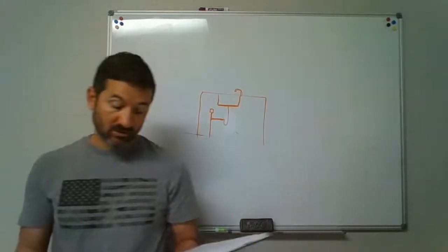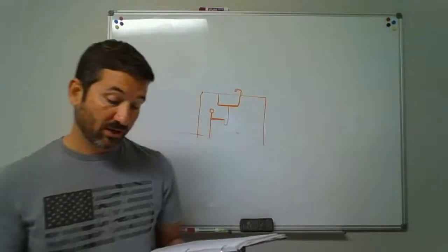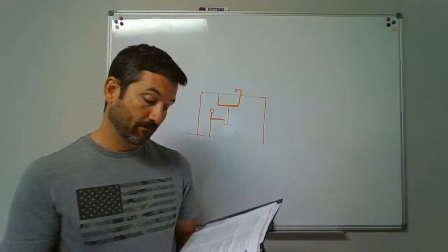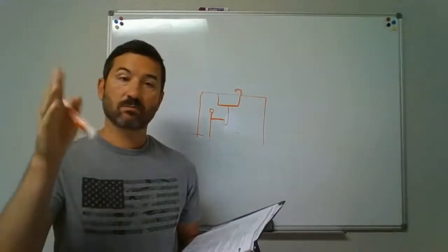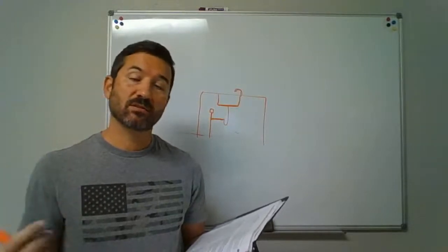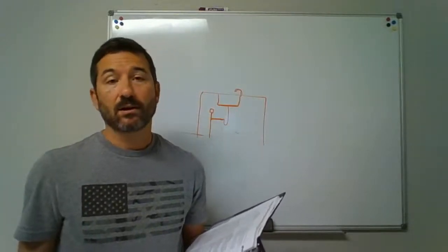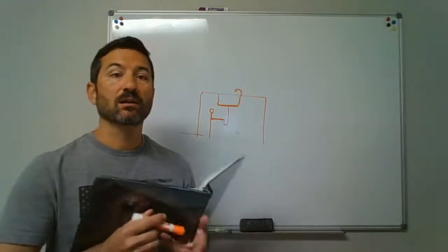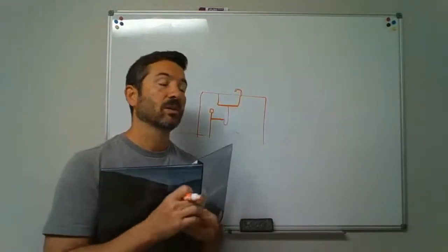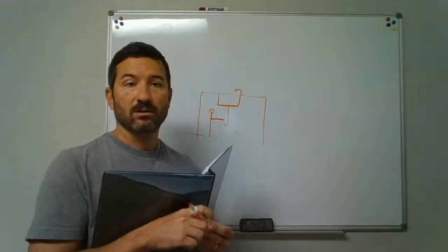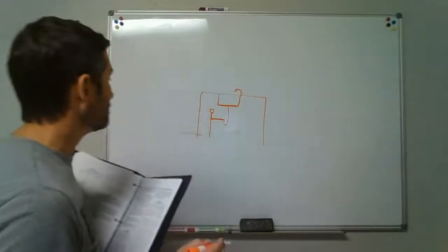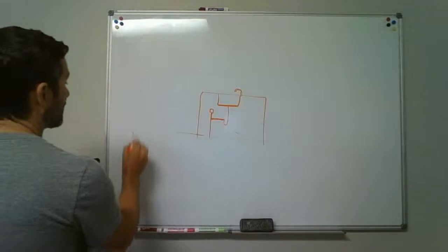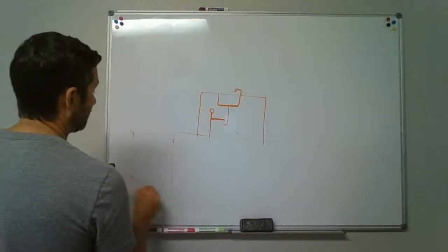Air admittance valves are permitted to be individual vents, branch and circuit vents. It can be used as that in between for a common vent, wet vents, anything. You can't use it as your main. And then you also cannot use them on, let's just say we had a tank, a sewage ejector. Those sewage ejector tanks have to be vented.